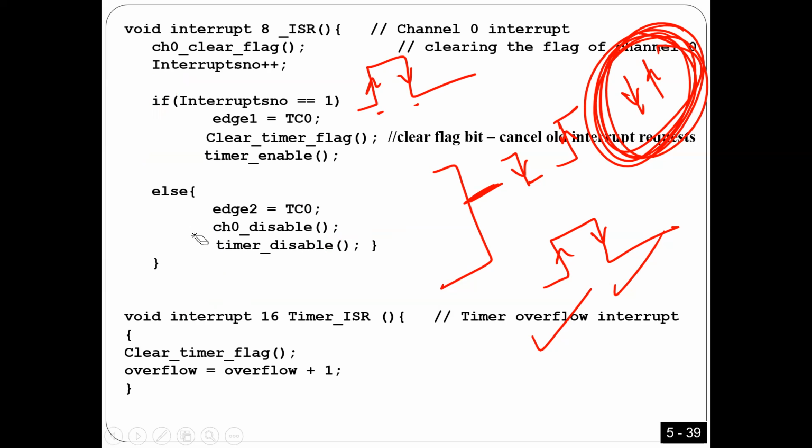If you have a signal like this, for example, and I want to measure the time from here to here, there is a risk. What is the risk? If I start measurement from here, the first rising and falling, I'm going to measure this one, which is okay. However, if the signal was here when you start the measurement, you are going to measure the first rising or falling, because it's an or. Do you get what I'm saying? This one or this one. So the interrupt happens here, and I'm going to measure this one instead of this one.